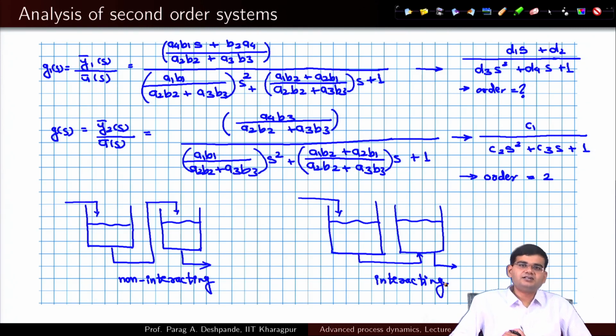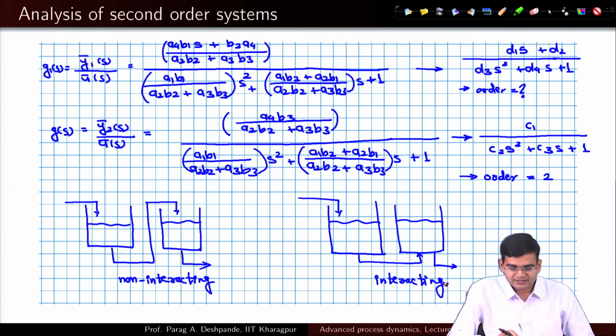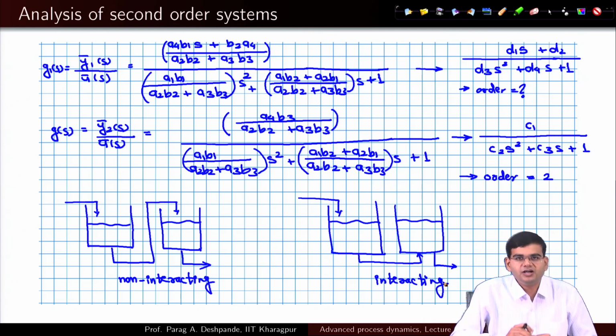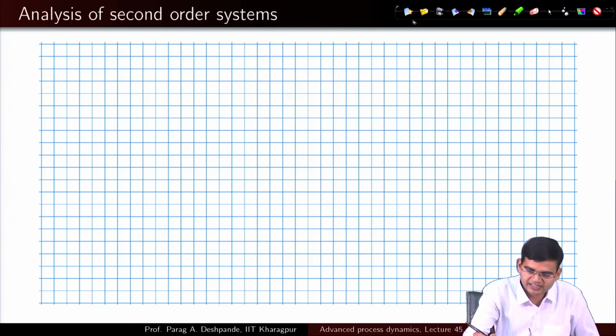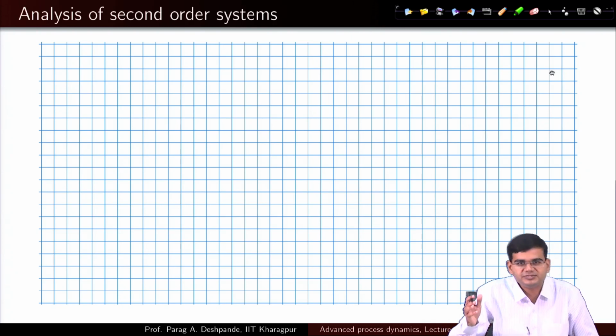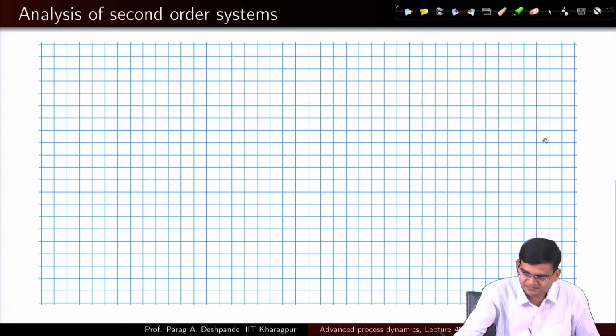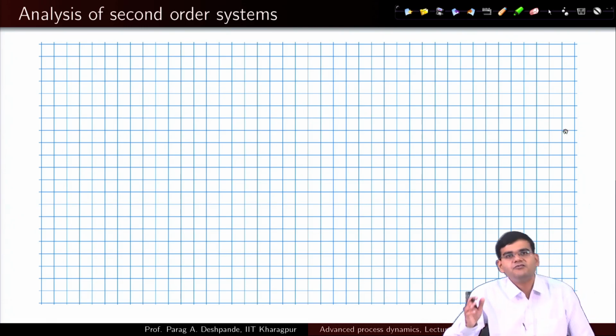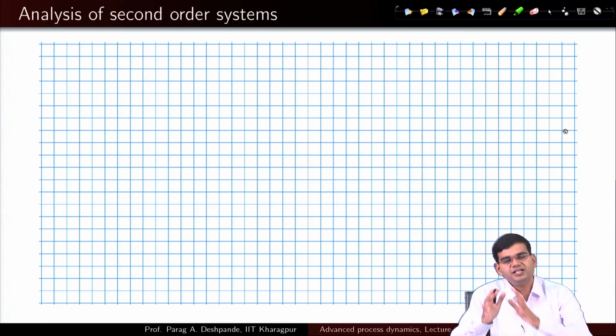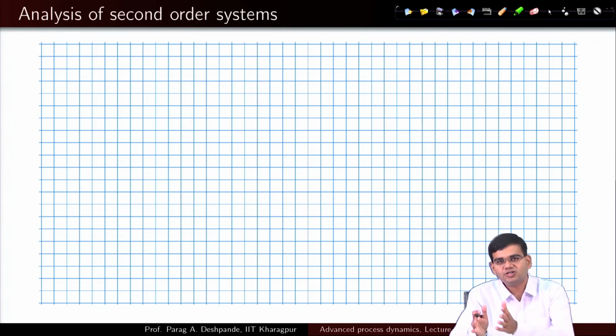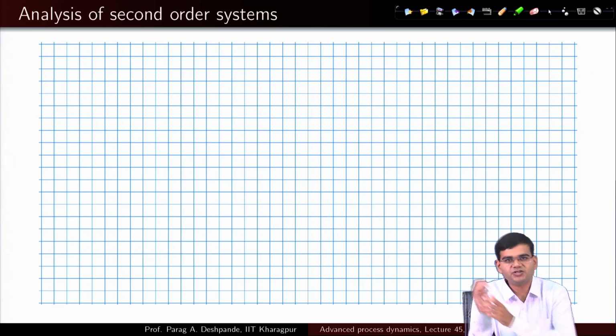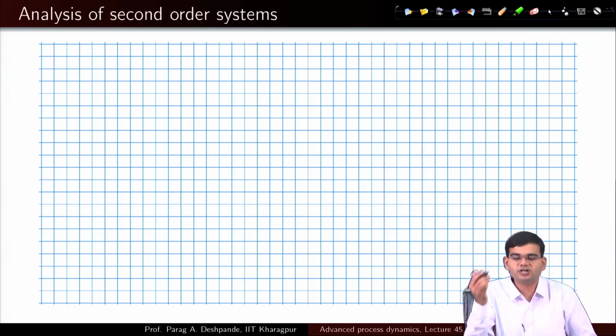We will study the dynamics of such systems a little later. But what you saw in general was that the dynamics of a second and higher order system is sluggish compared to the dynamics of a first order system, and it is guaranteed to be sluggish as well as monotonous when you simply have the multiplication of individual transfer functions as the overall transfer function.